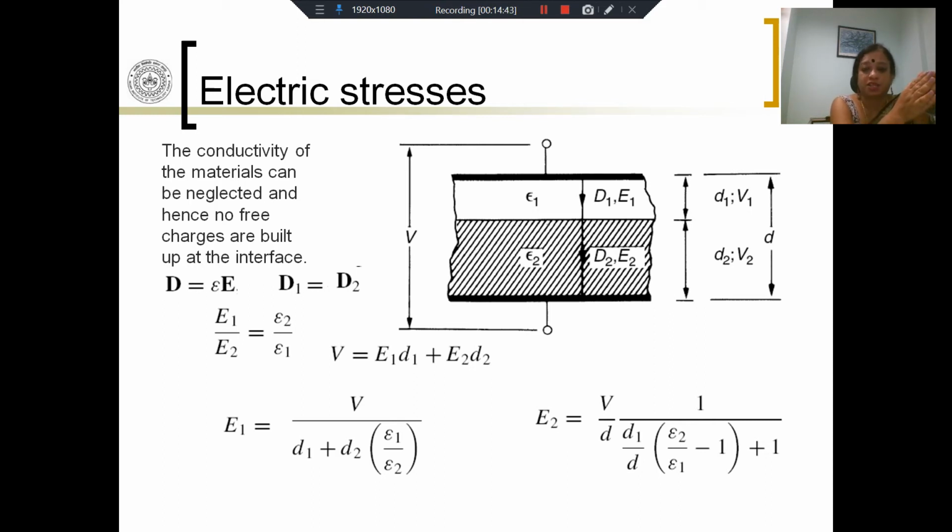Those charged particles will impinge on the second dielectric material, and by some complicated processes which we will discuss later, they can damage the second dielectric material and can lead to complete catastrophic failure of the entire material. Even if it doesn't lead to complete failure, it will lead to decreased functionality. You will have an inferior capacitor than you bargained for.